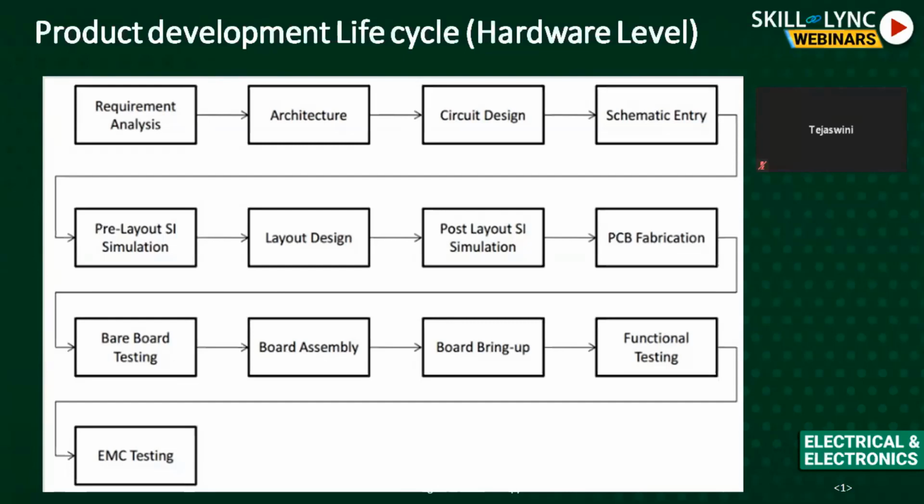In industry, we do the circuits with respect to modularization. So we break down the complete circuit into different modules, and then each module is given to different engineers. So we do the circuit design for each module. And once all the modules are done, we finally integrate every module into the schematic entry. And again, if required, pre-layout SI simulations, signal integrity.